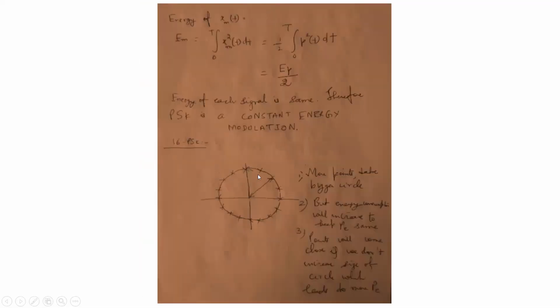All right. So that means every signal can be expressed in terms of the basis functions, with a_m and b_m being the coordinates of the signal points. So how do you get a_m? a_m is given by cos of 2 pi m divided by capital M, into root E_p by 2. b_m is sine of 2 pi small m divided by capital M, into root E_p by 2.